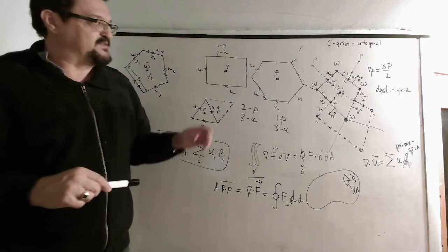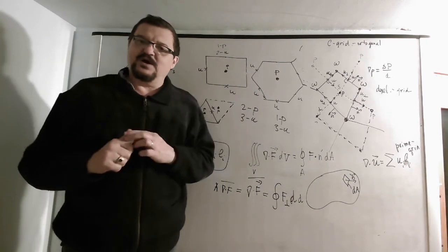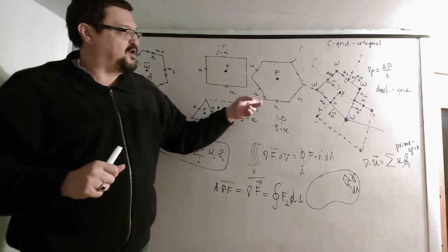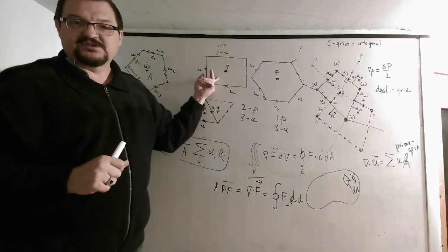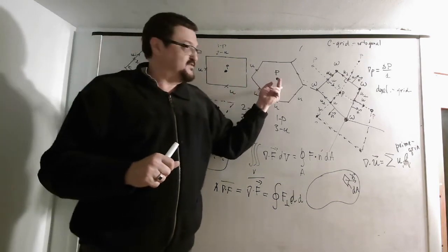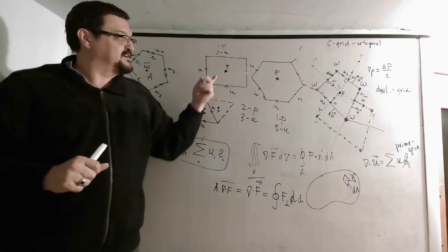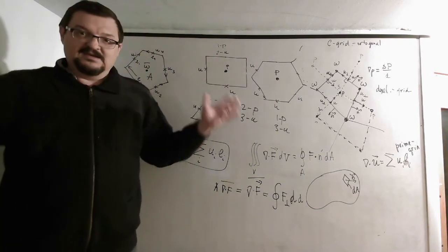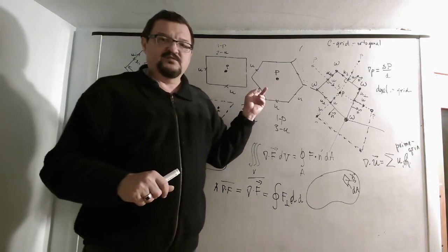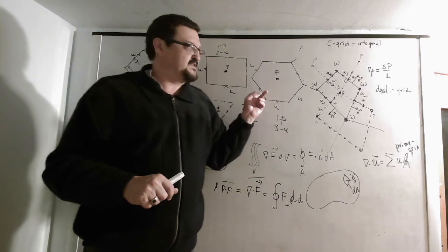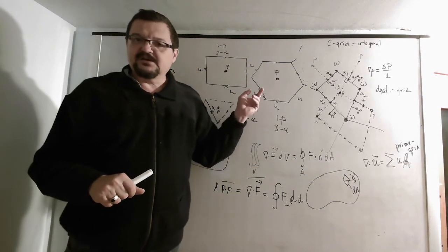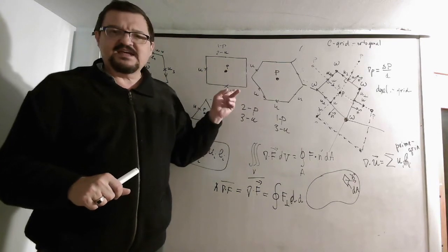Of course, that's the drawback. This is basically why using grids that contain, say, triangles or hexagons instead of quadrilaterals is problematic from this point of view. Although there are some advantages of this approach and triangles compared to this approach on some complex geometries, you need to be aware of this problem, so-called computational modes in space, and they can be controlled.